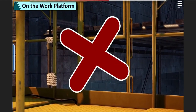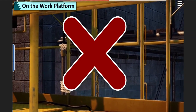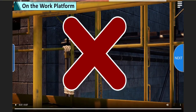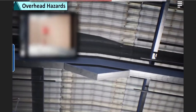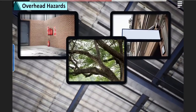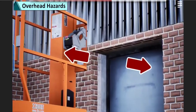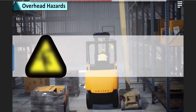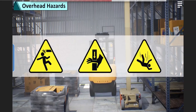Never attempt to steady the platform or improve stability by positioning the MEWP against, tied to, or restrained by another object. Objects above and beside the MEWP, such as ceilings, walls, signs, trees, poles, and electrical lines, can all pose a significant risk. If there isn't enough clearance, or if the work platform or other object moves for any reason, it can cause struck by or caught between injuries to workers, as well as falls from the platform.